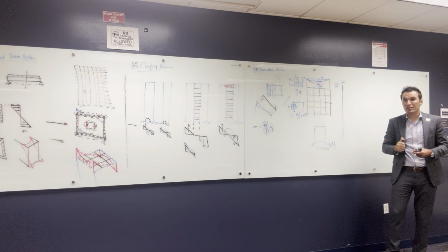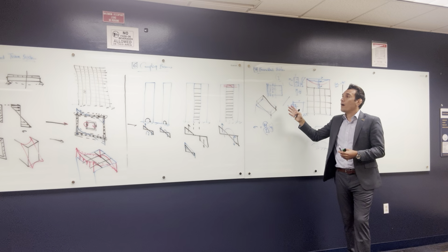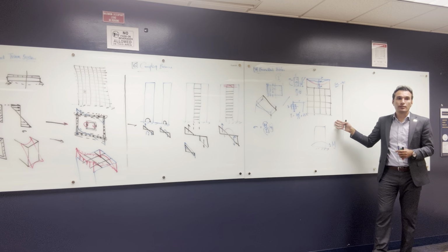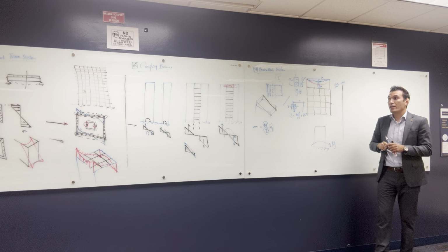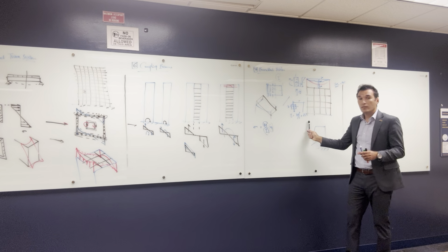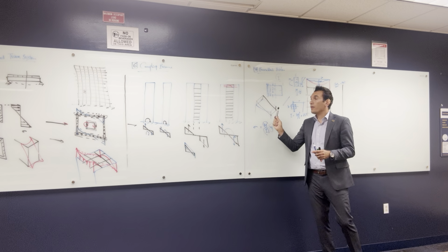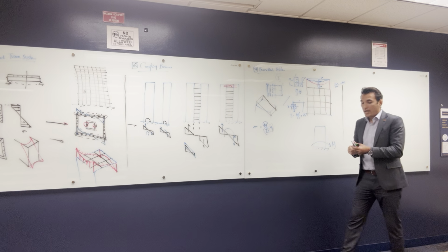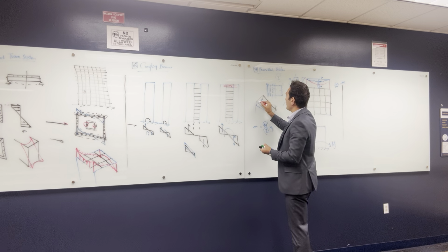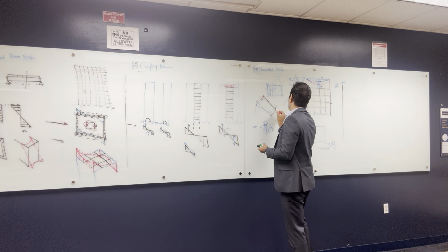And this is going to be a bonus in the project. If you try to find out what the zero shear lag system, or the perfect system, is and compare it with the lagged system and see what the difference looks like, you are going to see what your layout looks like. Then start to apply this rule for each building, and then you start getting the stress at each column, and you will end up having this linear behavior. And if you want to plot both the lagged system with the perfect system, it's going to be, for example, something like this.